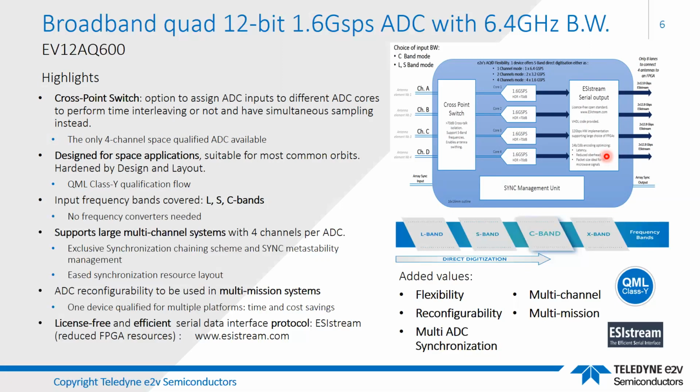So that's a big advantage for systems that need lots of channels and need lots of internal resource on the FPGA to be able to interface to the ADC. The other interesting thing is it's got a low latency. It's not a high latency interface. And I'll speak about that and deterministic latency in the next couple of slides.